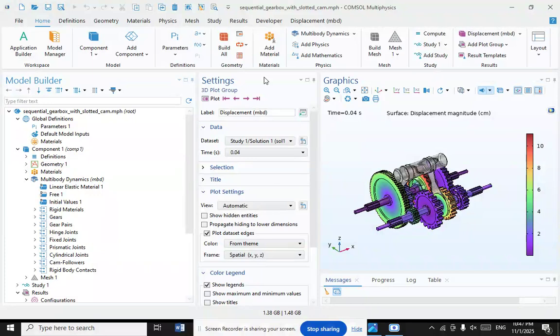When the engine is running and the clutch is engaged, for example clutch pedal up, the flywheel spins the clutch pressure plate and hence the transmission. The design of most manual transmissions for cars is that gear ratios are selected by locking selected gear pairs to the output shaft inside the transmission.